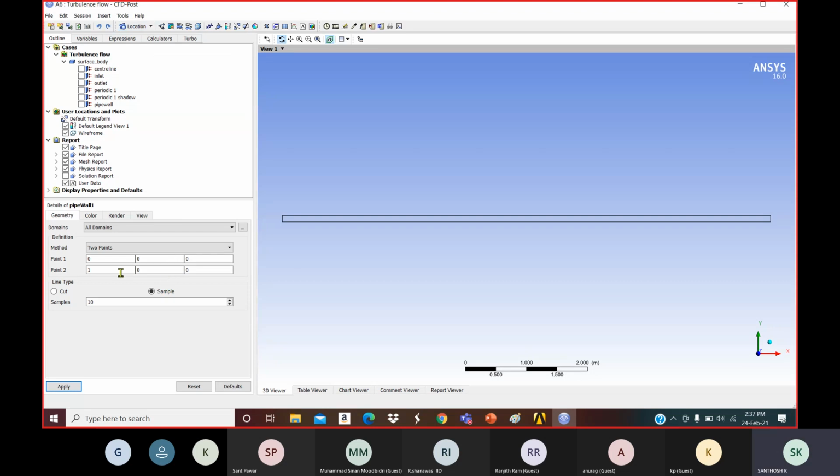At which region? It is very easy, like the absolute coordinate system if you are good at AutoCAD. This is only a surface, so it has only 2 coordinates and no Z coordinate. So I'll go over here: 0, 0.1, and the other point is 8, 0.1. This is the way I'm going to create it.